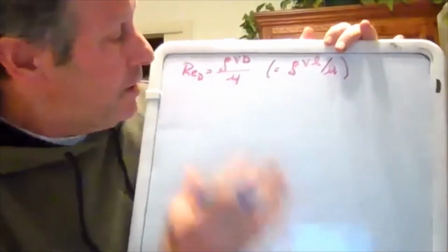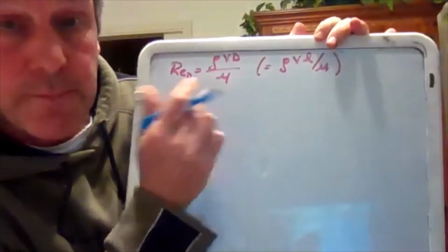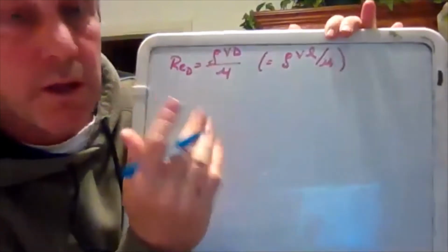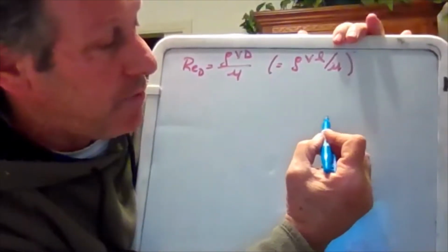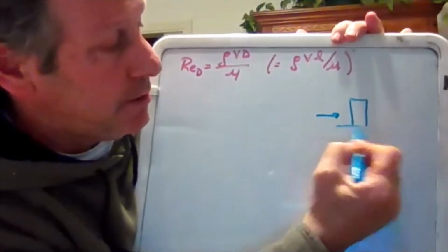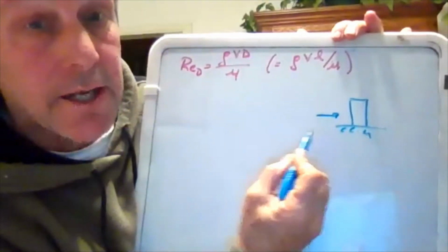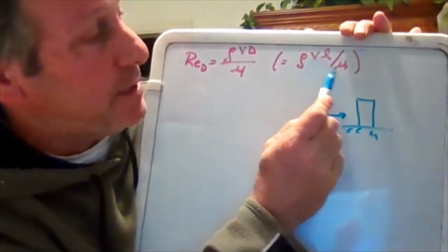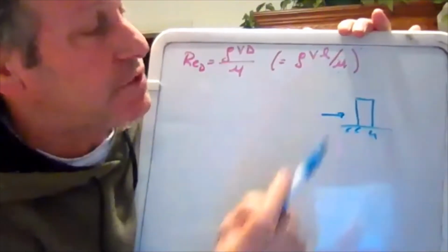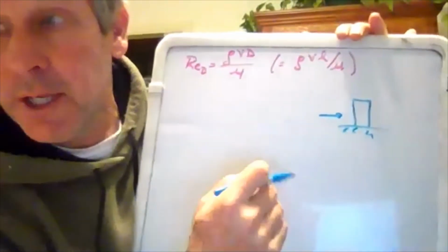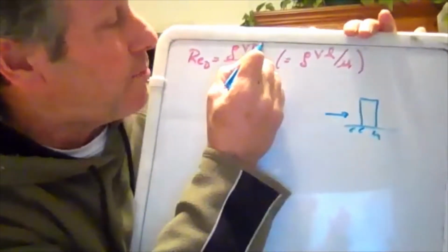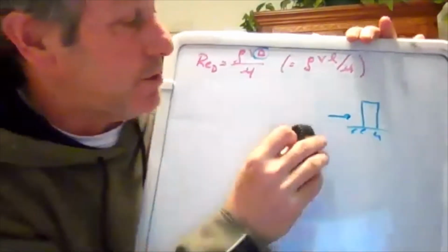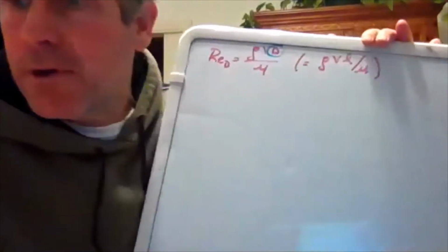All right, so that's the basic relationship for Reynolds number for a very particular situation. Subscript D, this is for pipe flow. In general, for any situation we have, so if we have wind approaching a building and going around a building, we're going to get a Reynolds number for that to help us evaluate whether there's turbulence. And in general, the parameters we're going to use are density, speed, fluid viscosity, and then some sort of length associated with the geometry, some sort of distance associated with the geometry. For our particular case, it is the pipe diameter. So get rid of that building. We're not doing buildings. We'll take a look at external flows in chapter 9. Right now we're doing internal flows.